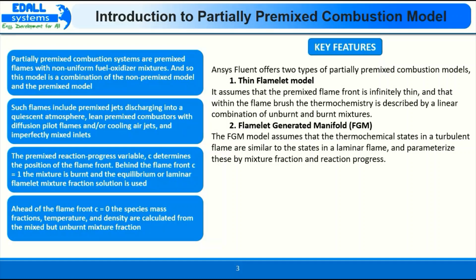The key features of this model: Ansys Fluent offers two types of partially premixed combustion models, that is the thin flamelet model and the flamelet generated manifold. The thin flamelet model assumes that the premixed flame front is infinitely thin and that within the flame brush, the thermochemistry is described by a linear combination of unburnt and burnt mixtures. Whereas the flamelet generated manifold method assumes that the thermochemistry states in a turbulent flame are similar to the states in a laminar flame, and it parameterizes these by mixture fraction and reaction progress. So one has the choice of using either model.